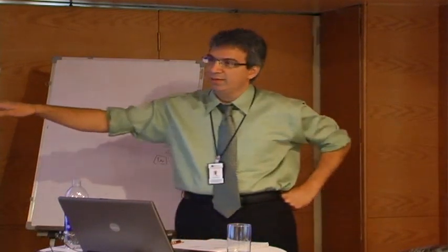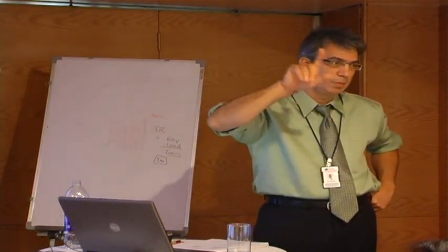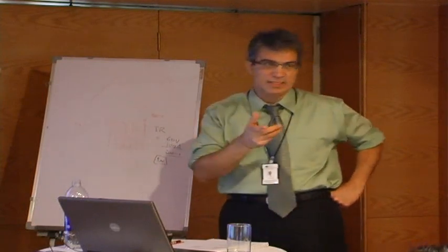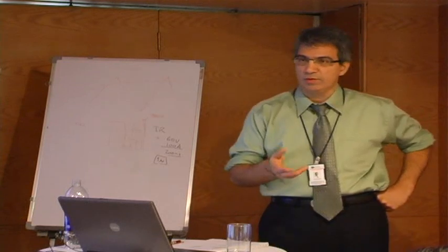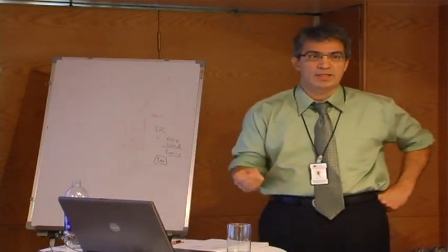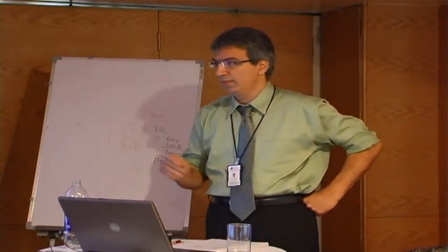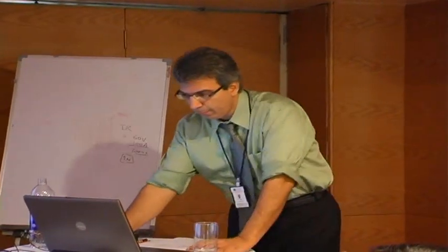Otherwise, you get inaccurate results on the PWM generation. That's needed anyhow. If you're doing transient analysis, time analysis, that's something you have to pay attention to: what is the maximum time step for simulation.